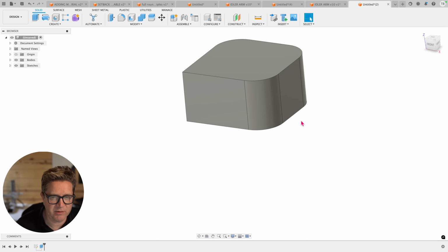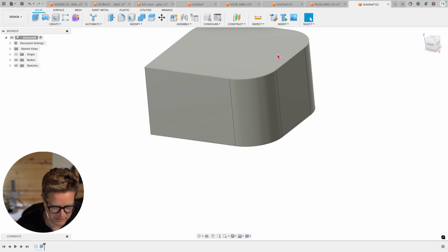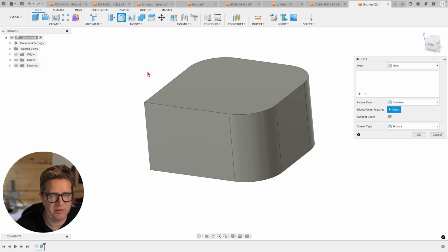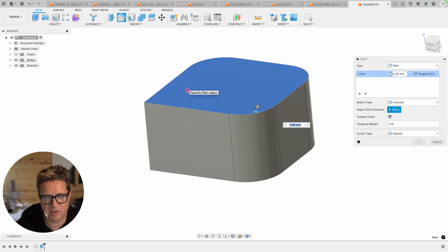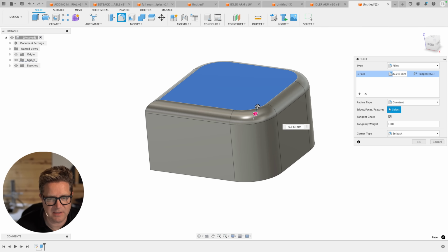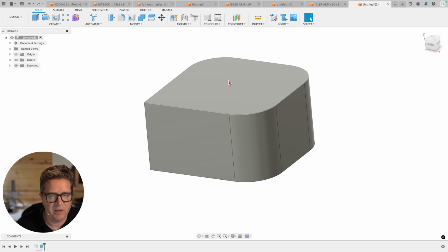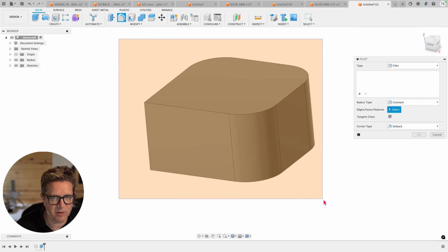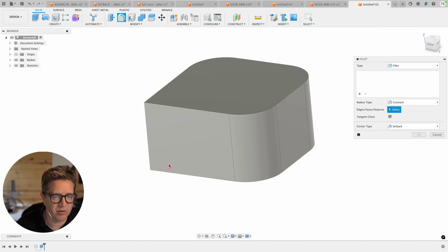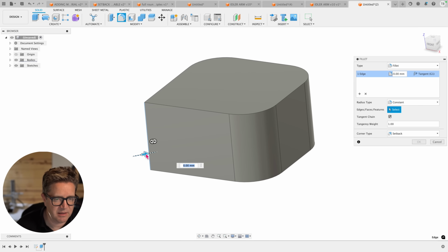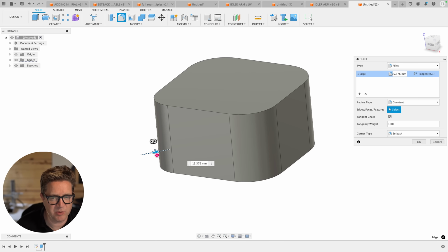But where I really like the feature fillet is that on this model, not only can we add fillets to all the edges and faces like we've been talking about, we can select everything at once and add these fillets. What I also like is its editability and the ability to see it happen on the 3D model live. So I can adjust this on the fly.